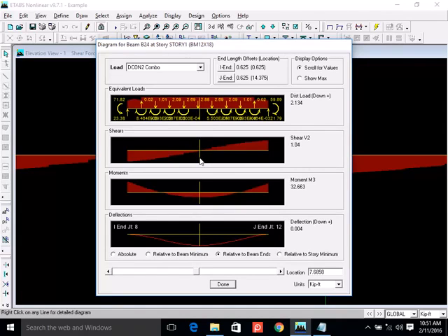You see that? 0.94, or if I am a little finer, then we may catch 0. But at the center, shear is approximately 0 or minimum, and moment is maximum, which is around 32 kip-ft, right? And at the support, you have a negative moment like this, -71 is the negative bending.